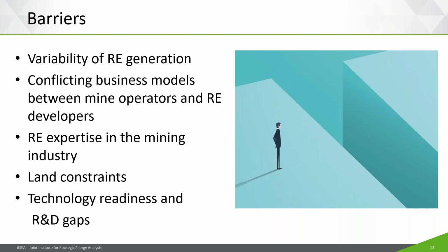general. Some of the barriers that we have heard from the mining industry and that we have uncovered in our research to incorporating more renewables. Number one is the variability of renewable generation. And I've got a couple slides after this to illustrate that. But certainly when you've got constant loads and generation that's variable, and storage is still a technology that might be out of the money in terms of economics, or not provide you with the duration of storage you might need, this can be something that the mining operators are finding a challenge in incorporating more renewables. So it's not an easy one-to-one swap. You have to account for the variability.